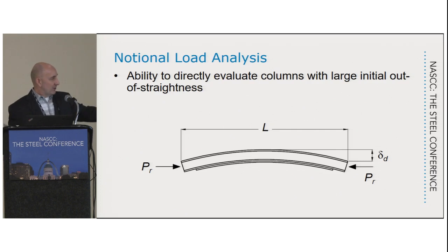But if you have reinforcement on both sides of this flange, they can kind of stagger their welding. They can weld, and I don't know, I'm probably getting this wrong, they can weld here and then go up and weld over here some and then come back and weld here to limit the distortion to that member caused by the weld shrinkage. And with this single-sided reinforcement, you're not going to be able to do that quite as much. There's only a limited amount of things you can do.